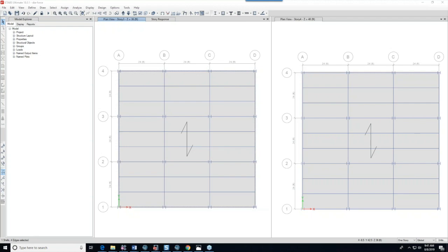One other thing to remember about constraints, if you go back to our very first part of our discussion today, considering two joints, if you have two joints which are constrained and you have a lot of force that's potentially being generated between those two joints, if the joints are constrained, there's no way to find out how much force is being transmitted between those two joints. So it may be necessary not to use a constraint, but to put in a very rigid element. And then that way the program will report the forces in those elements so that you can determine how much force is being carried between the constrained joints. But that's really the only way.